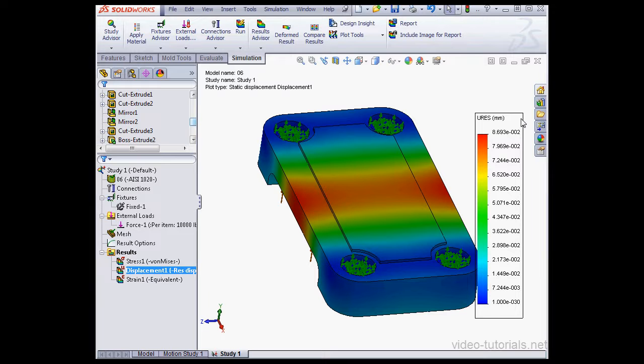Now, on the other hand, it's important not to go overboard with the suppression of features. If you're not sure whether the feature affects the integrity of your model or not, just leave it unsuppressed. The more experience you have with SolidWorks simulation, the easier it gets to simplify a part without compromising the integrity. At minimum, it's going to certainly speed up your time working with simulation.